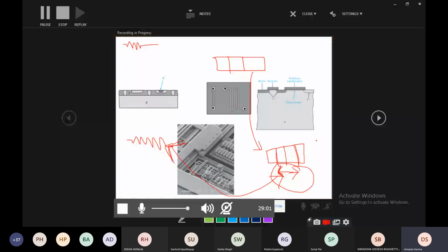So how is that done basically? During implantation, that is base implantation, right? Where is the base? Here is the base. When there is base implantation, a resistor can be implanted, which is made of a very thin p-type layer with one of the n-type islands.